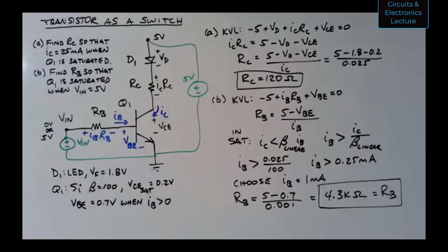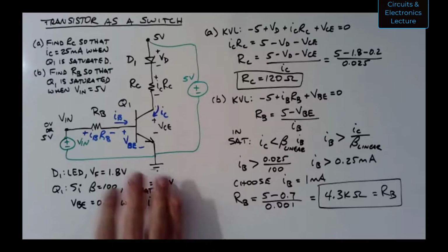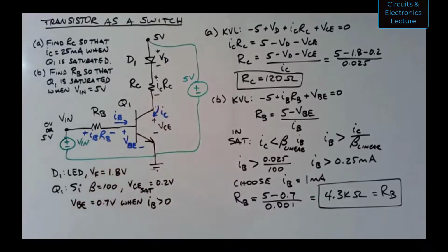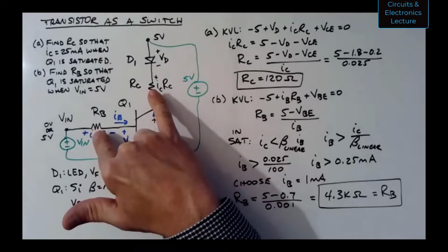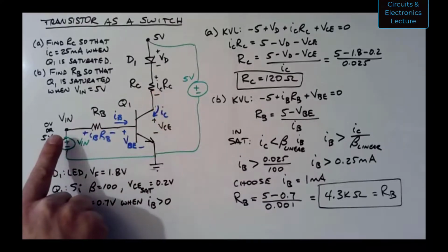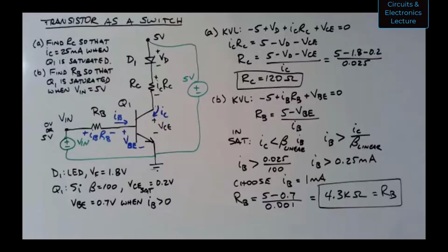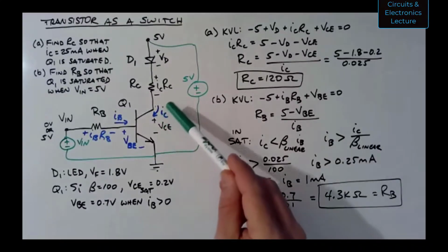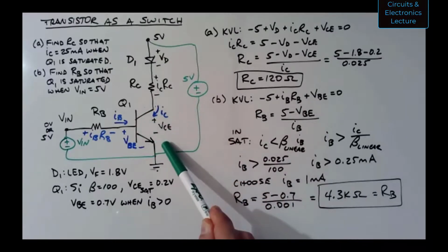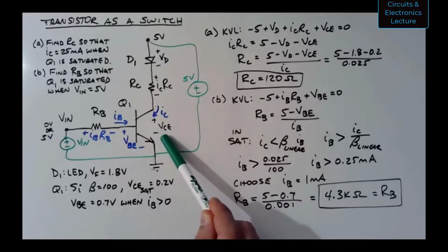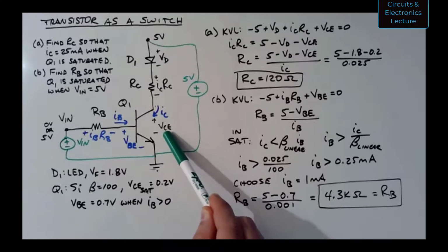Right. You can come at this problem from a couple of perspectives. This was designing for those resistor values. You could also ask the question, if I were given resistor values, what voltage Vin would saturate the transistor? There you'd have to figure out what IC, just like we did on the previous whiteboard where I drew out that table.